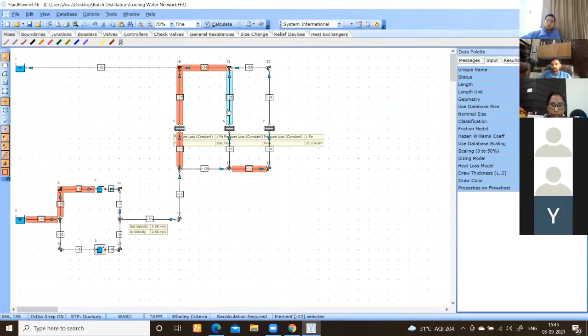All right, run it. So there is one 2-inch I saw. 5-inch, I don't know. Somewhere I saw second exchanger outlet, 50 meters. Second exchanger outlet, yes, sir. These are also 5-inch. Are they supposed to be 5-inch? Second exchanger outlet is 2-inch, no? So make it 5-inch. Okay. So the pump discharge length is 50 meters.